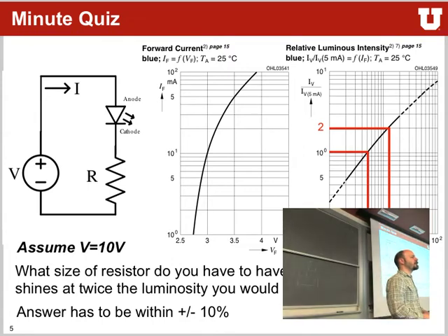Yes? I had a hard time finding out what the rail voltage was going to be on the board. Is that something that's pretty defined? Depends on what you hook up to it. If you hook 5 volts up, stuff will start smoking because your MSP is only rated up to 3.6 volts. Generally, if you look at the data sheet, the MSP will run anywhere from about 2.1 volts up to 3.6 volts. So it really depends on what you provide to the whole board, since we don't have a regulator on the board. Most of the time, it's 3 or 3.3 volts, but it's up to you to decide.